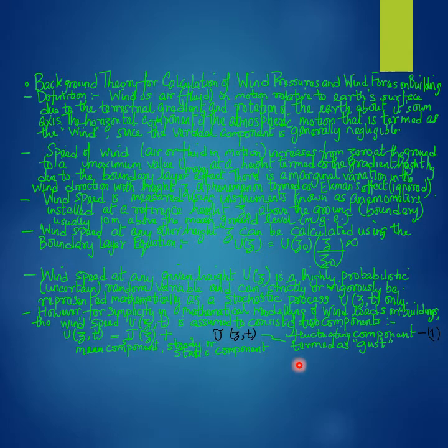Therefore, to conclude the discussion on the mathematical modeling of the design wind speed, or the speed of air, that is essentially a fluid in motion in the atmospheric boundary layer, the wind speed at any general height z based on the principles of boundary layer flow can be represented using the polynomial equation presented here, that is the traditional boundary layer equation for mathematical modeling of the speed of a fluid in a boundary layer.